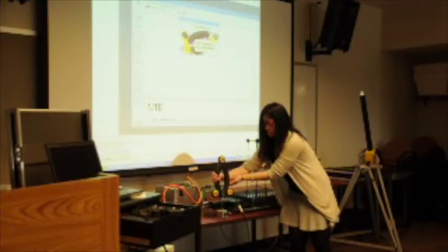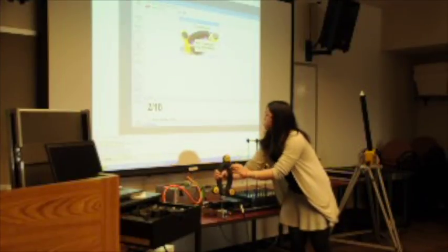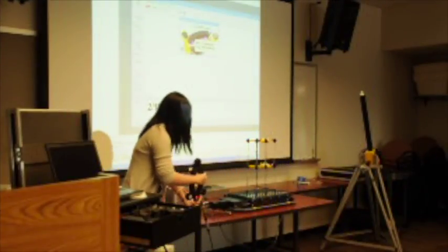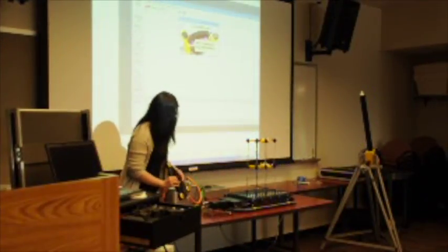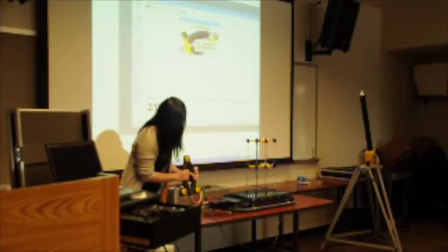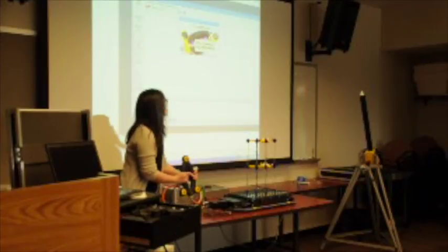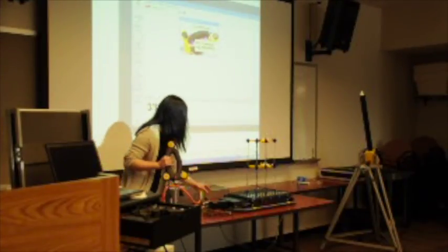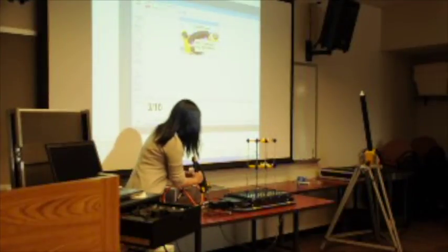So basically what you're doing now is defining a plane that is parallel to the surface of the table, using those points with the aid of the magnetic things. So basically we are defining a plane, a line, and a dot, and we will use those to define our system. What is our origin, what is x, what is y, what is z.